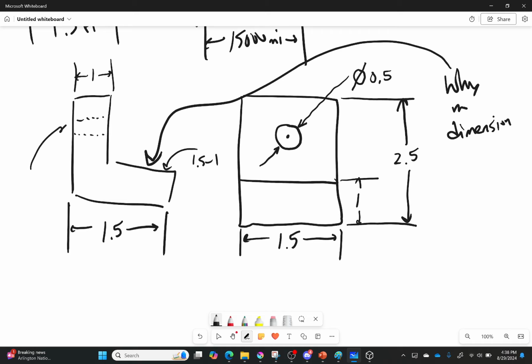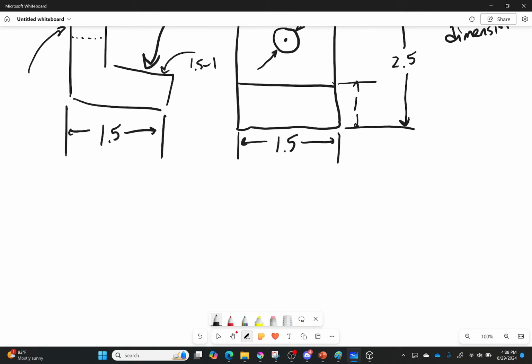I've talked a little bit about these lines here, but now I think it's about a good time to start specifying a little bit more detail about lines we add. There are various different lines we have in drawings. The one you're going to see the most is the solid line. It's big, it's thick, it looks like that. You can also have an extension line, okay? So we have the solid lines. Those are for the edges of my drawing. Then we have extension lines. These simply extend, and they're usually used to tell me where edges are for dimensions.